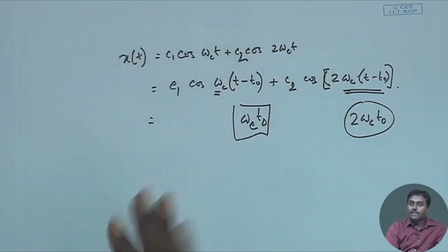If I was passing it through a delay element, that is the case, whereas when we pass it through a Hilbert transform, both of them will get an equivalent phase shift, all pi by 2. So they will have equal phase shift, but the delay will be different for different frequency elements.